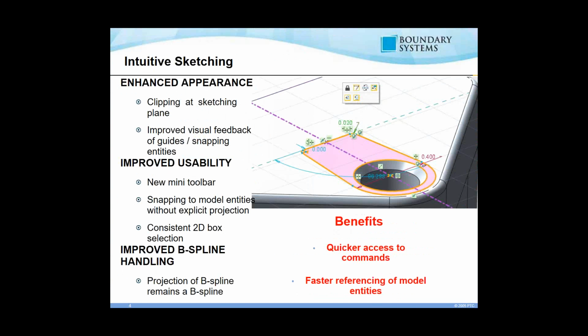The other improvement is you'll notice in this case here in the screenshot, wherever you see the constraints inside of Sketcher, for example, over here, this coincident constraint, they all highlight inside of a small green box, which makes them easier to see as compared to Creo 3 and older, where the constraints themselves would just highlight and they were much easier to miss because they were sort of yellow and blending out with a white background, and you would inadvertently add constraints that you didn't want to add because you didn't know that they were there when you were sketching.